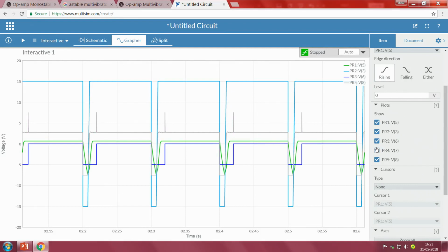Now I do not need it, but we can observe one thing: when I give a spike, the negative voltage is somewhere around 664 millivolts, which is almost equal to the 0.7 volts diode cut-in voltage, right. Whenever I give a negative spike, the blue color one is a negative spike for somewhere around 10 milliseconds, right. Since this is passed to a differentiator, it has generated a negative spike of 10 milliseconds.